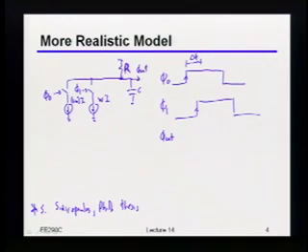Exponentially settling. Yeah, it's going to be some exponential settling, right? But there's actually going to be two exponentials here, right? Because first, when this first phi 0 goes high, there's going to be some first exponential there, where the height of that exponential is set by how much current you have in that branch, right? Then once this second one goes high, phi 1, you're going to have a different amplitude on that exponential, right?